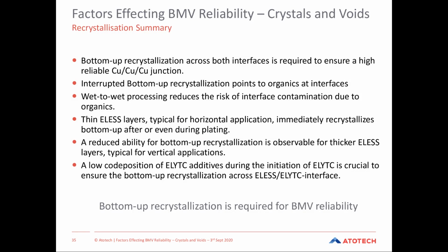So moving on to the summaries. In terms of recrystallization, bottom-up recrystallization is your best shot in getting the best via reliability. In order to achieve that, you have to have clean chemical surfaces and processes that are running in control. If you can minimize any chance of oxidation, so never let your board dry out, you will get a better performance, in terms of plating recrystallization. And we see thinner electroless layers perform better than thicker layers as well.